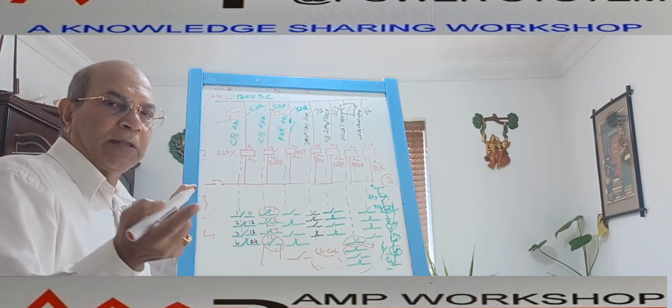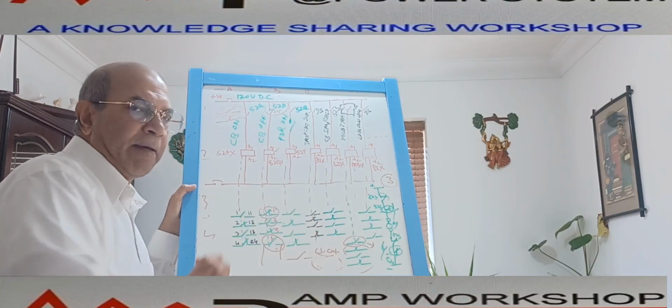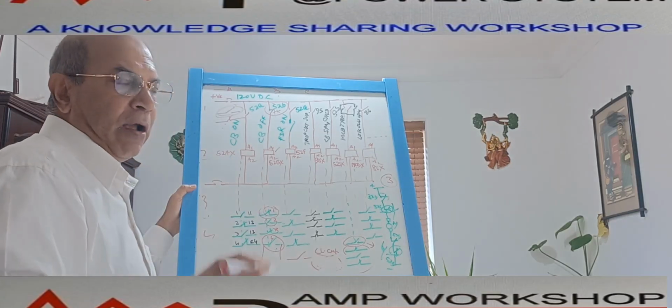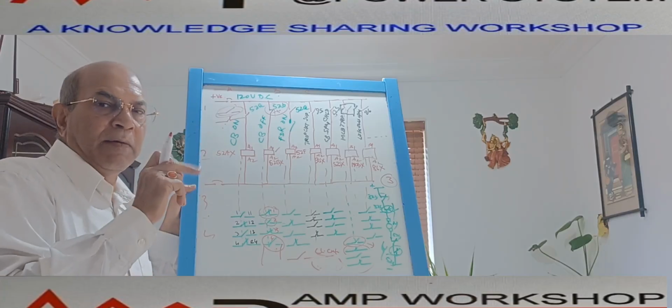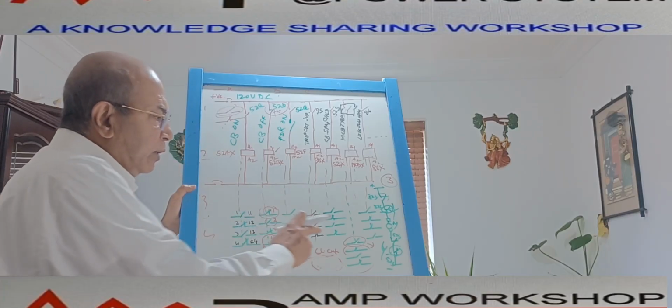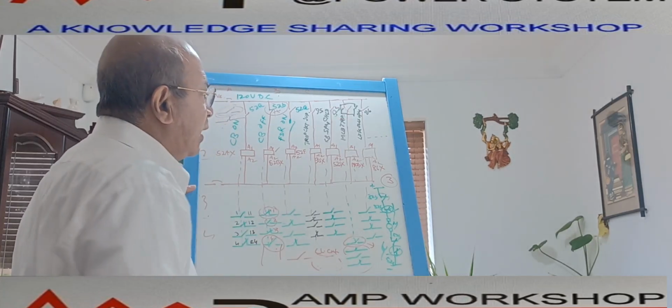Immediately the operator or the maintenance people will come and check why the alarm is coming. Then they will check all the MCBs. If an MCB has tripped, they can make it out from the MCB body itself, as a red color has come. So that's why this auxiliary relay is also required.